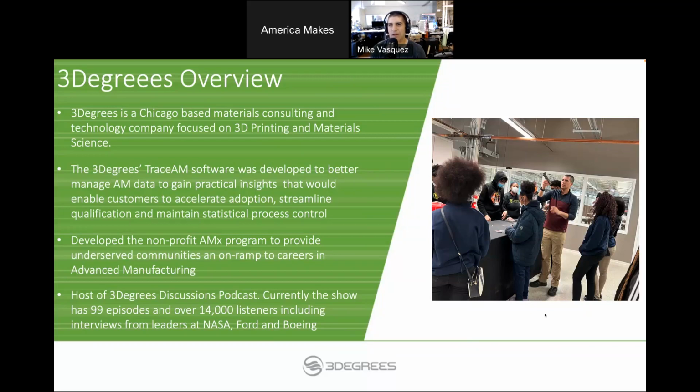I went around to 100 different companies. I kind of went in and said, hey, where are you at in your additive adoption phase? And then the second and third and fourth question was really about how are you managing your data? Like, how are you keeping track of, if you're going through qualification, the tensile specimens that you might be building or the density cubes that you might be putting into your machine on a day-to-day basis? Do you know what build those go to? Do you know what material lot number those were traced back to? And for the most part, they could answer yes, but it's going to take me a while.